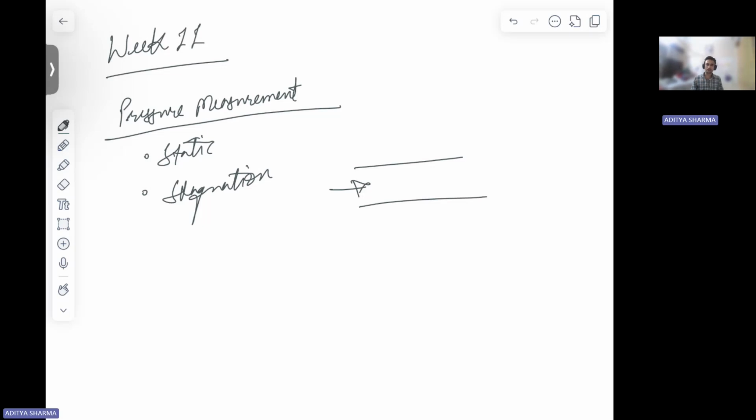There are two pressures involved here. One pressure is that which the wall is experiencing, and one pressure is by virtue of the flow of the fluid. The one at the walls is the static pressure. And because of the velocity is the dynamic pressure.